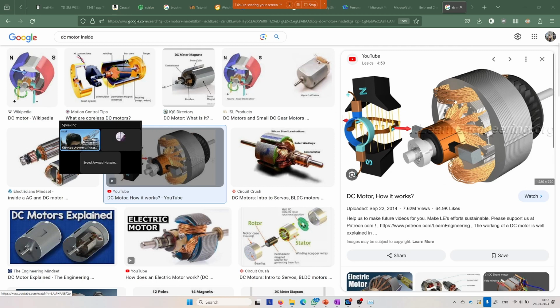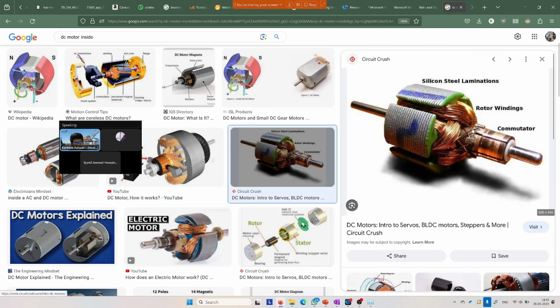On the right half of the image, we have this bearing which is carrying the shaft. The commutator part, these are the commutator brushes. This is graphite, and it can wear out over time. That's why you eventually have to replace the brush or the motor itself. So that's the commutator ring. These are the coils, coil windings, and that at the end is a fan for cooling for a big motor. But for a small motor like in this size, this is the kind of coil you will see.